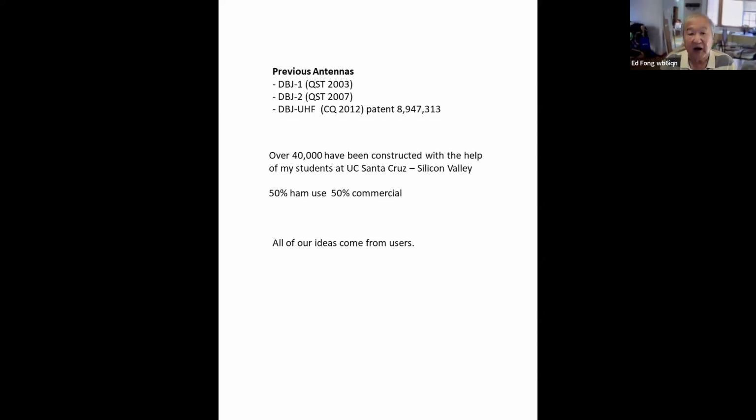So I wrote an article on how you actually get gain mathematically. There's no easy way out of it. You have to make a dual band collinear. That's a talk I give. It's pretty clever, and a lot of repeaters use this technique now. It's not that uncommon, but I mainly show how you do it, how you get gain, how you measure it, and how you precisely tune it to get the best gain possible.